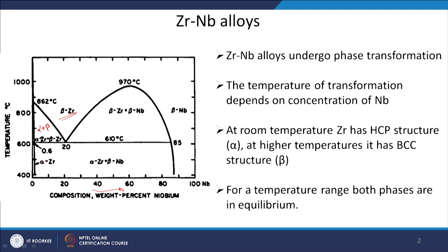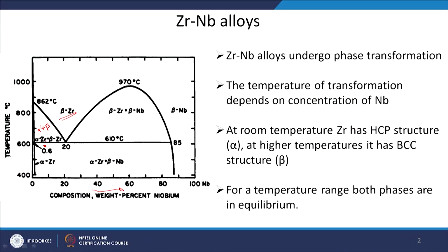We studied the whole transformation range for the deformation behavior, and what we saw in the literature is that people are developing constitutive equations without taking into account the different phases present at different temperatures. For example, I can do deformation at different temperatures here, and the constitutive equation will be developed for all the temperatures together, without taking into account the different crystal structures present at different temperatures.